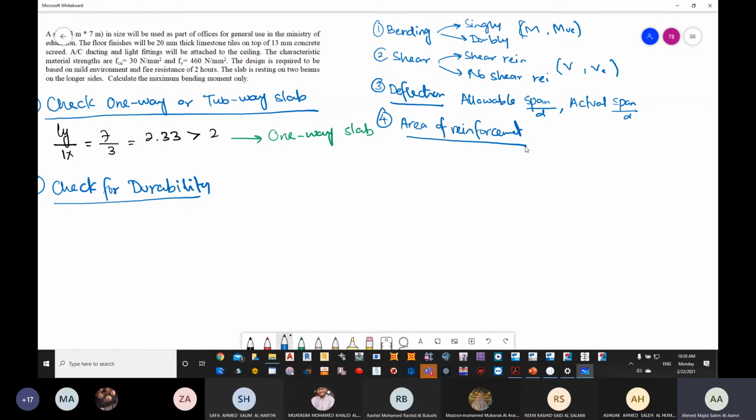We have two materials, one is concrete, one is steel, inside an RCC member. We are making sure our equations ensure that the stress of steel will reach the limit before the concrete.